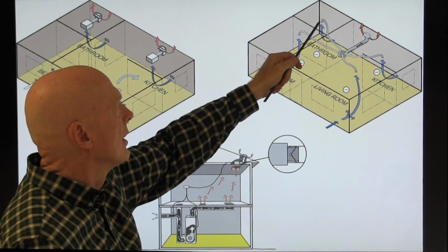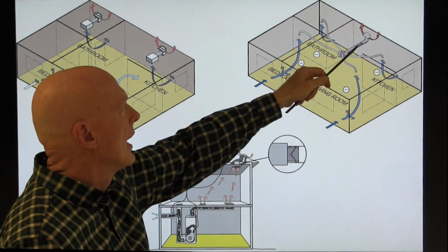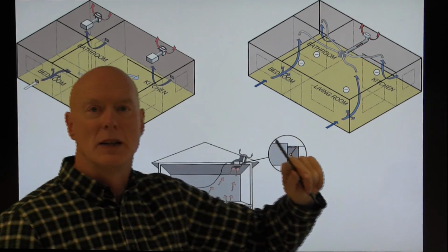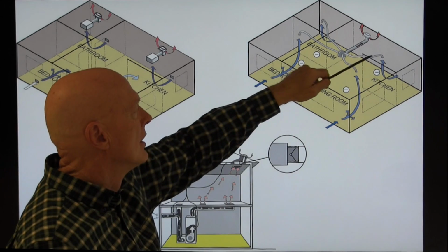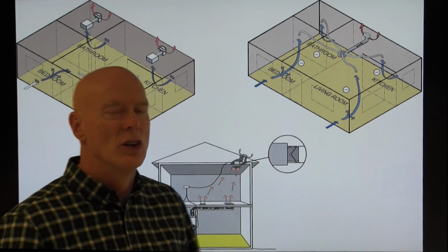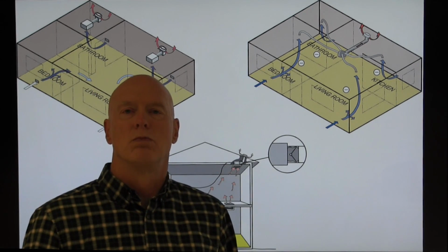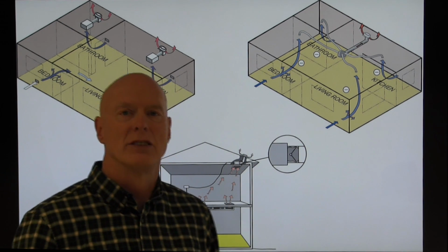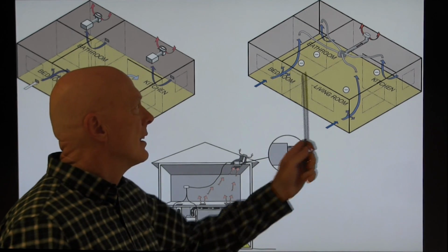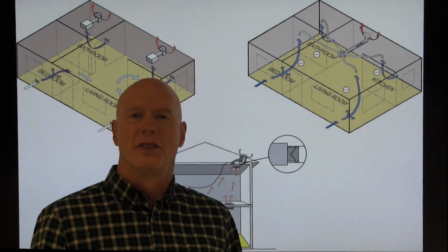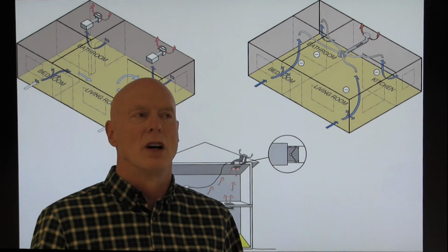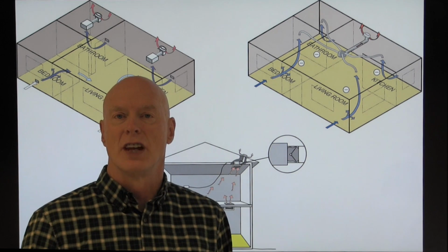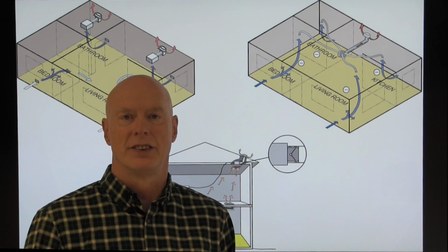The only issue here is, can the central ventilator draw enough air out of the bathroom to keep the mirrors from fogging? Can it draw enough air out of the kitchen to exhaust the air that we have when we're cooking, say, a Thanksgiving dinner? So these central ventilation systems often have bathroom fans and kitchen fans that are separate from the central ventilators.